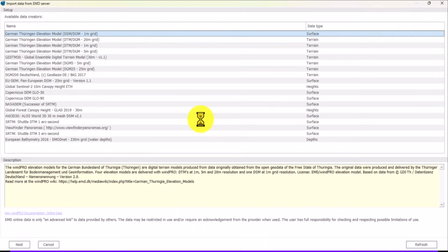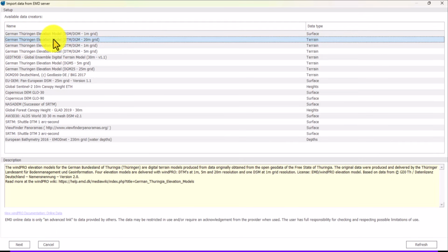Now I would like to access the online database. I would like to emphasize that we can use this object in order to get different types of elevation data like DTM, digital terrain model, digital surface model. Click add layer from online data, and then we have this window to get the data for all parts of Germany. You can access the local database here.